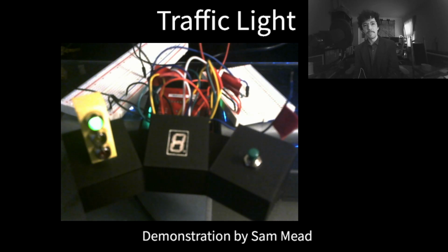Now, how I actually implemented this in the code, you will see better in the project report. But as a quick aside, I did not use hardware interrupts for this. I definitely could have, and it would be a great implementation of that knowledge. However, I did start this before we even got to that lecture, so I figured out a nifty way to do this, similar to how we did, I believe, lab 11 or 10. I'd have to look back at that to verify. It's essentially still using SysTick, but using the software timer.